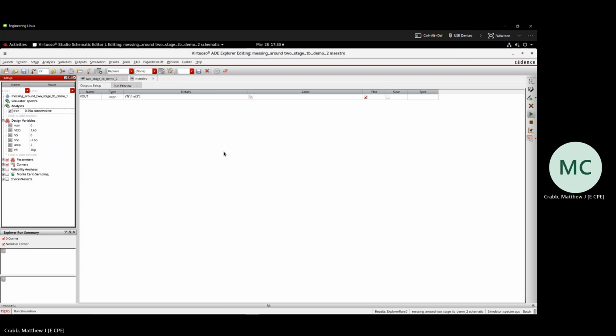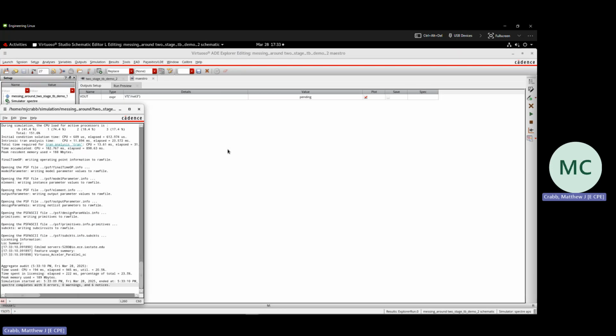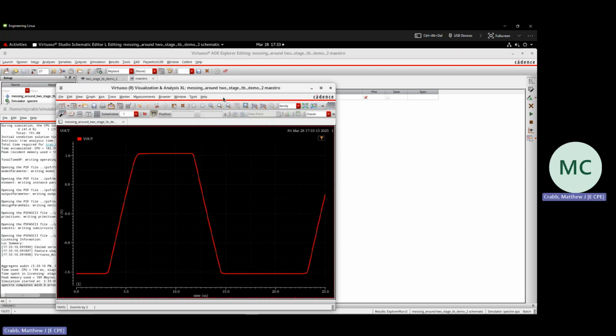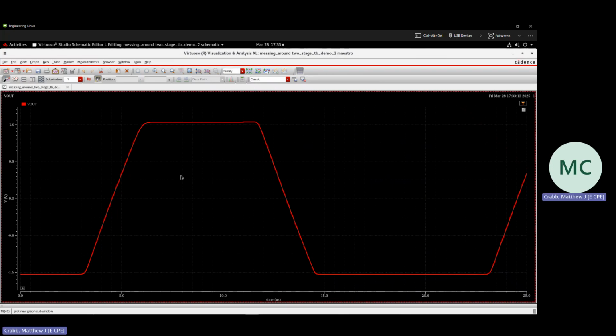Oh, it's running again. Remember, if something seems off, it's probably your fault. There we go. Okay, so now we can see I hit. Well, it looks like I set up my source wrong because I'm basically just saturating from rail to rail here. It looks like for my negative slew rate, I become very linear. Looking at this, I start pretty steep and then become less steep.